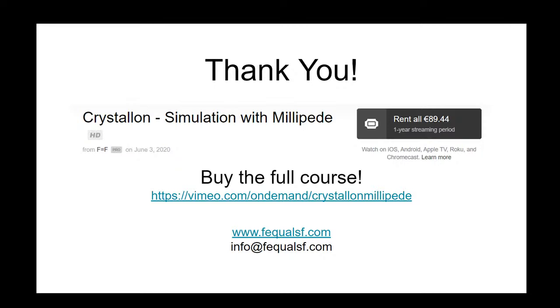Oh, we've got one question. Someone asked, some of the deformations are pretty large. Does the program handle large deformations? And the answer is no. Something like Karamba can do large deformations, but you need an iterative solver. You need something nonlinear to look at large deformations. So it's not great for that. It's really just a linear static solver.